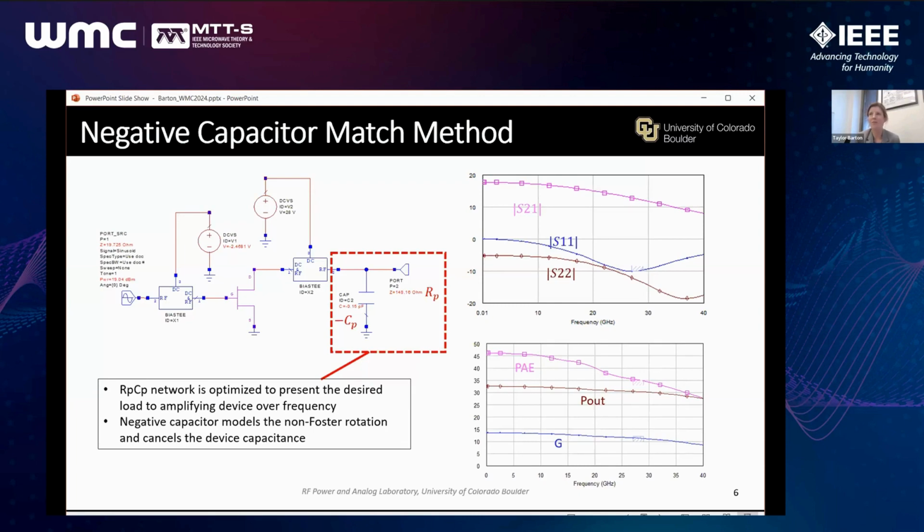It's really a model for the impedances that we want to present to the device, with a simulation setup that looks a little bit like load pull, but is more of a direct solution instead of a brute force, just load with every possible impedance and see what happens. So the schematic for that is shown here.